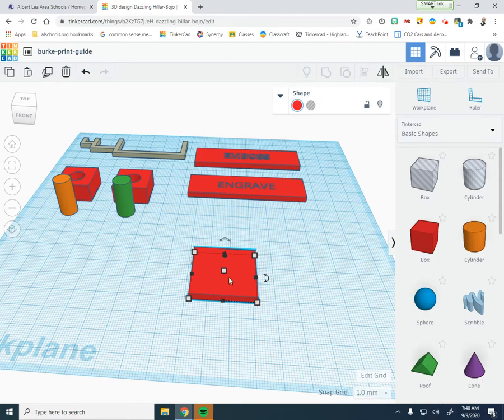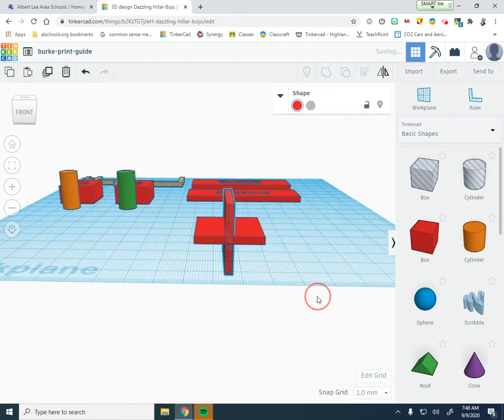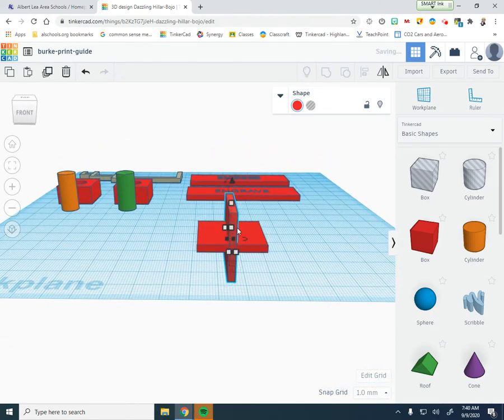So now with our bookend, we're going to duplicate this shape. Control D to duplicate it. And then we're going to rotate this on its end, because it's going to make just a square bookmark. So we're going to make this 90 degrees. So there's our bookmark. Now it just rotates directly on its middle, so it's right there in the middle, which we don't want. So we're going to raise this up a little bit, and once we get this raised up, we can do our alignment here.